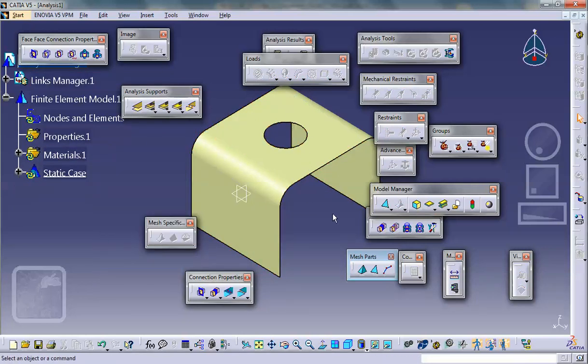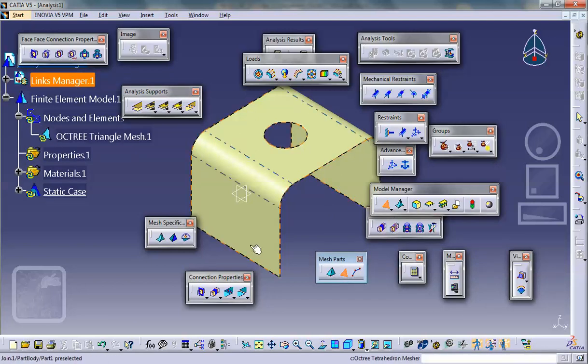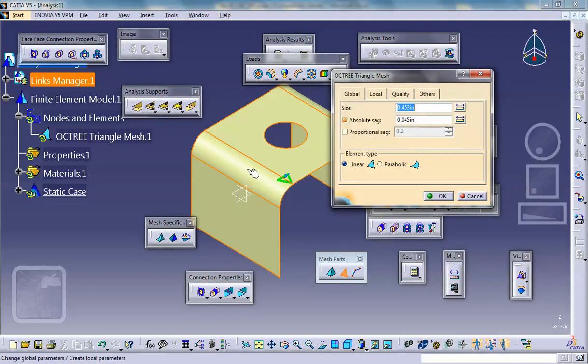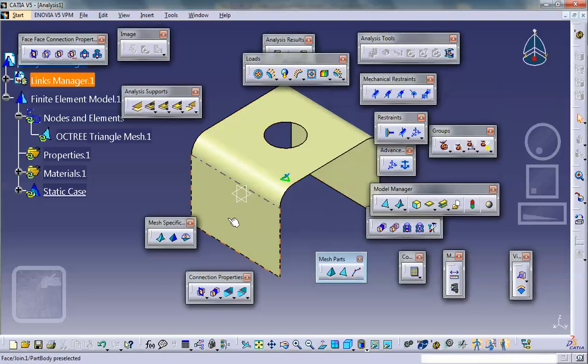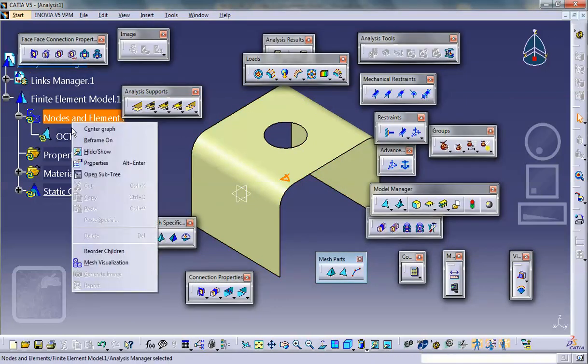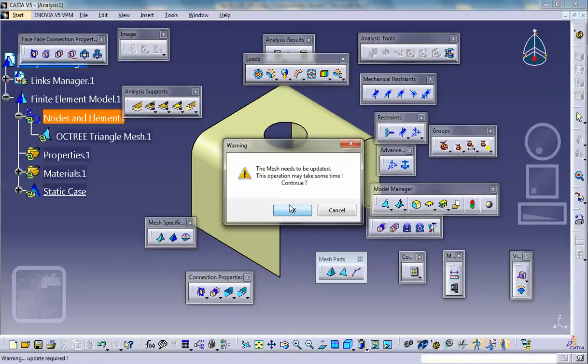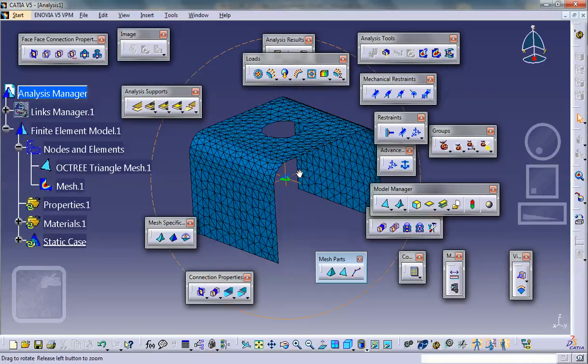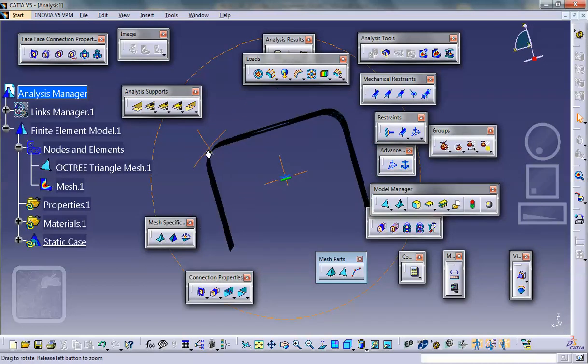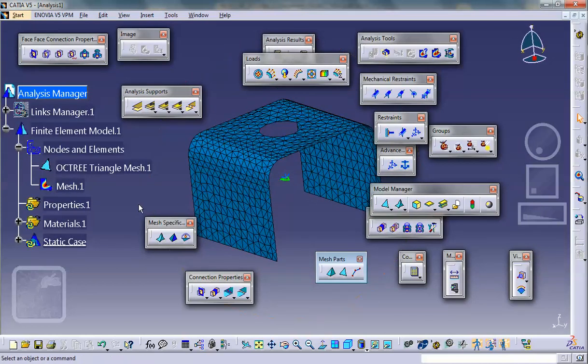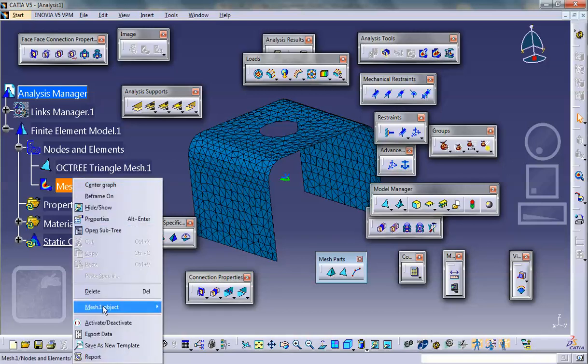Now, we have to mesh this thing with shell element. The shell elements are in the same place that you find beam elements. So click on the shell. Because it's joined, they're all going to be meshed at the same time. And let's make it 0.3, for example. All right. If you want to see the mesh, right-click, mesh, and there is my mesh. Notice that there is no thickness because these are surfaces and these are shell elements. Okay, so deactivate this plot.